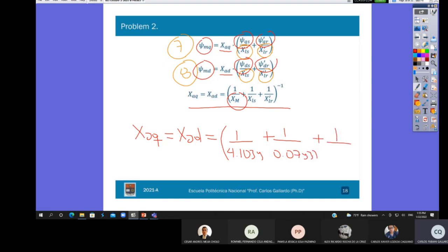And the last one, the rotor reactance, is 0.4. I will have here the inverse, and this value is 0.065177 per unit. So substituting this value here, I will have A unknowns and A equation. But in this case, I don't need initial condition because it's linear equations, okay? In the previous set of equation, I have a nonlinear equation. In this case, it's linear equation.